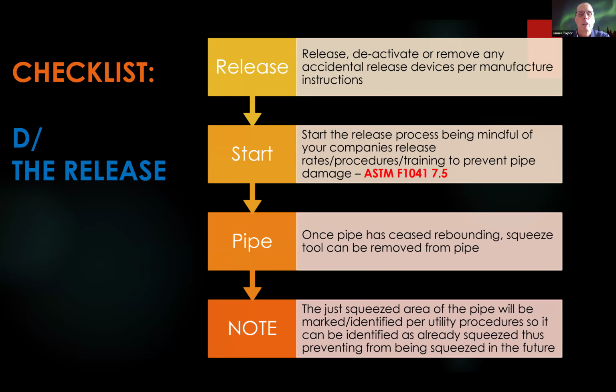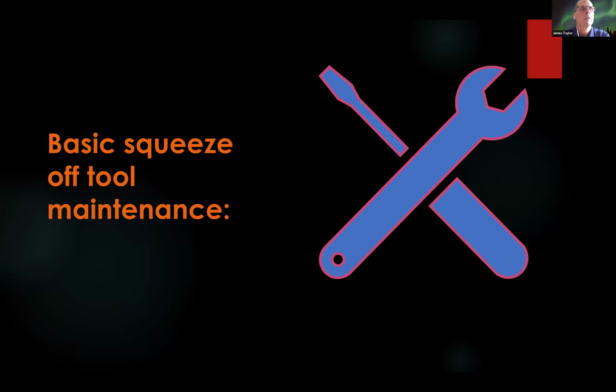And then keep the static grounding spike in the ground until the tool is removed from the pipe. We don't want any chances of anything. As we're gassing up again, as Dirk's going to talk about, so again, raining on his parade, gas is really screaming back through there again. Once it gets going and we start opening it, there's increased risk for static discharge. We'll go to the next one, please, Dirk.